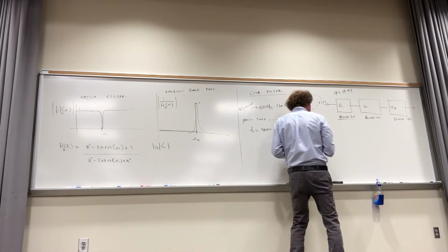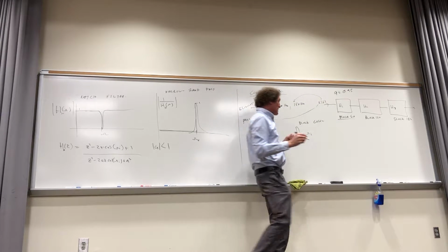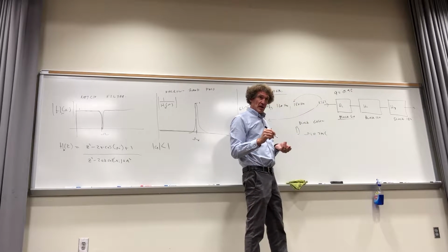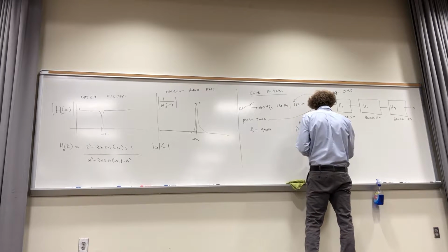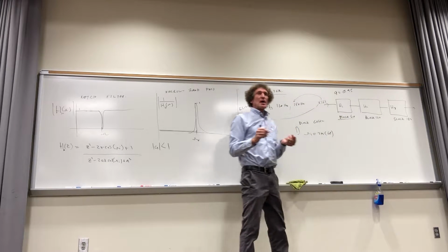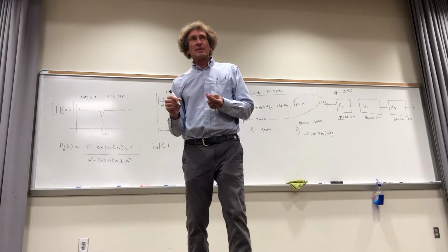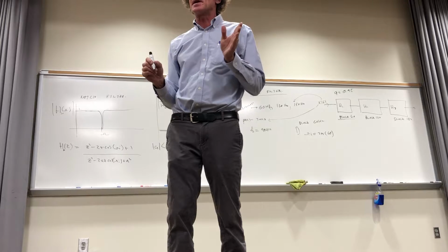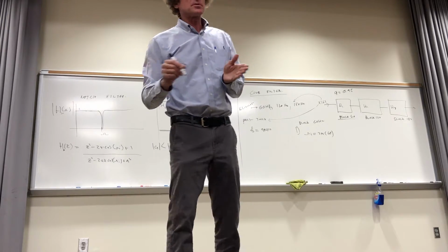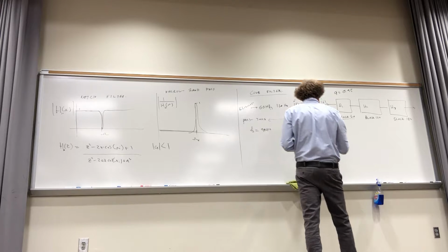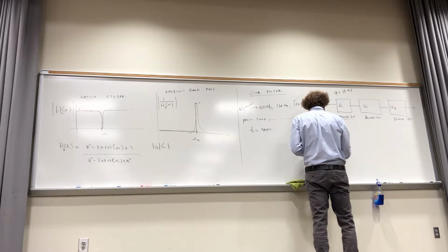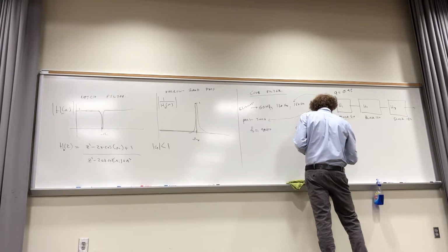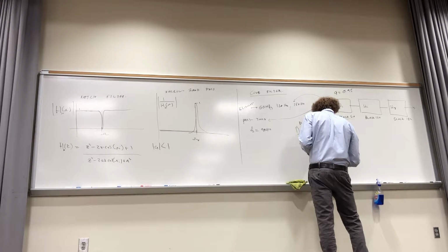Next thing I find is omega I, right? What is omega I? It's 2 pi times the frequency I want to block, correct? Which would be 60 in this case. Now, normally it's multiplied by the sampling period, TS. But that's the same exact thing as dividing by the sampling frequency. Does everybody understand that? The period is inversely proportional to the sampling frequency. So you might as well just put Fs down here, right? And therefore, omega I here would be equal to 2 pi times 60 divided by 480, right?